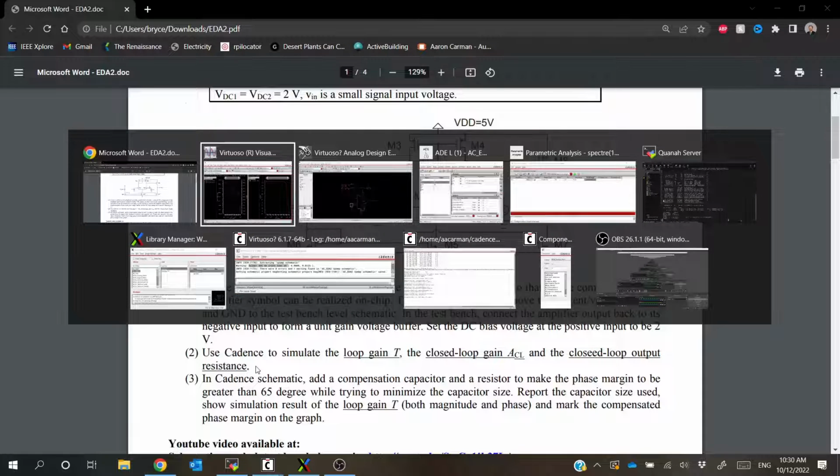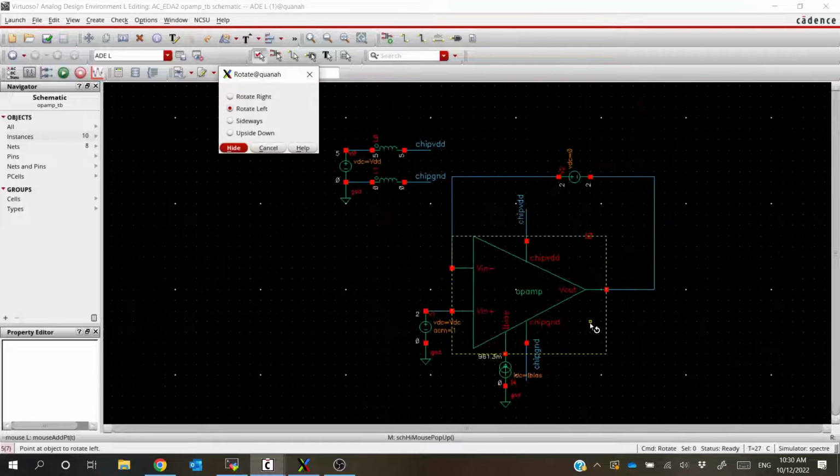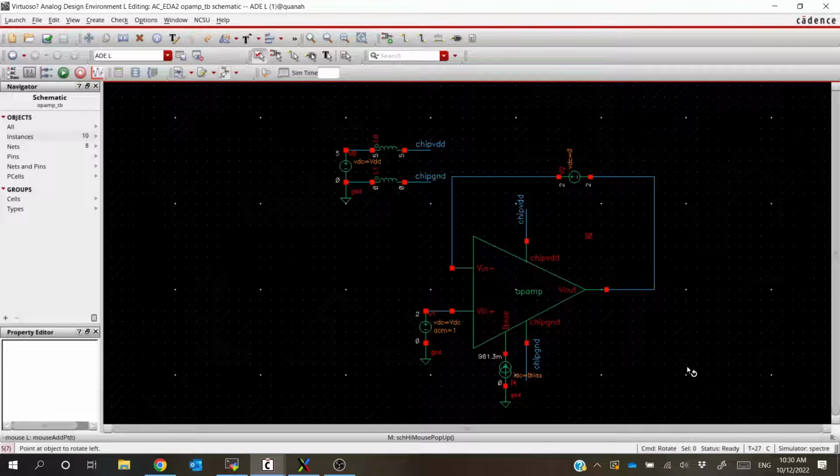Now, there's lots of different ways that you could do that. If we're going to measure this versus frequency, some of them will involve adding something like a voltage source connected to the output with a large enough isolation, like a capacitor between the two, to measure what kind of current in we have at various AC frequencies. But we don't want to have to do all of that stuff. We want to make our lives as easy as possible. And the way that we can do that is using XF analysis, which stands for transfer function analysis.